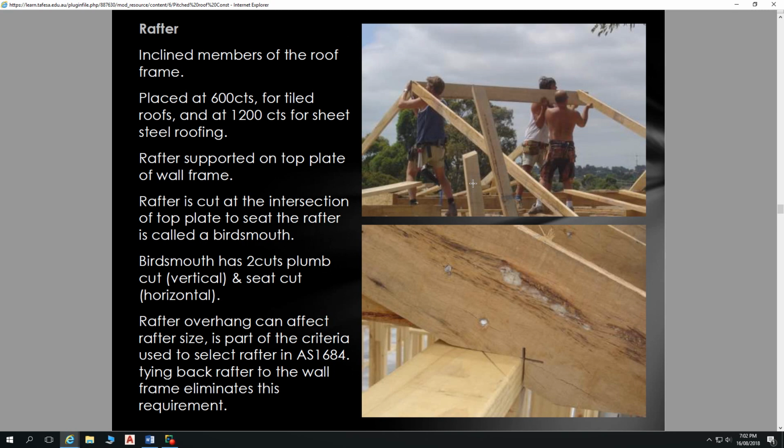So you've got one person getting around the site with a nail gun and some spare timber, long pieces of timber. They'll hold up that ridge, shoot a nail into that with their temporary bracing, hold that ridge into place while they form up the end, and then go and form up the other end, remove that temporary bracing, and then fill in with the rest of the rafters. So that's what's happening in here.